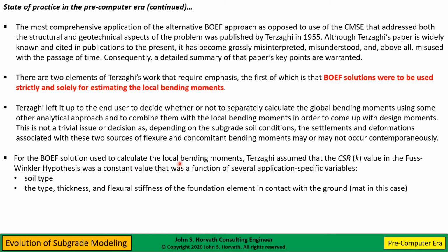And this is why I said in the prologue that generations of foundation engineers chasing after trying to link coefficient of subgrade reaction to fundamental soil properties, it's been a waste of time and money, because it's a function of, yes, soil type, but also a function of the foundation element in contact with it, as well as the load case. As I said earlier, you have the same problem, you vary the load case, you're going to get a different distribution of subgrade reaction.